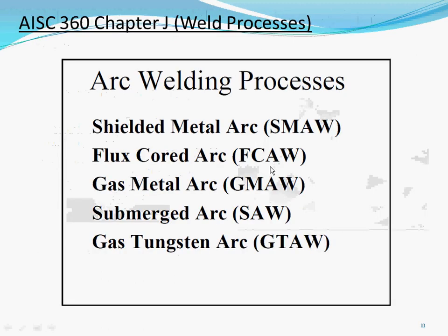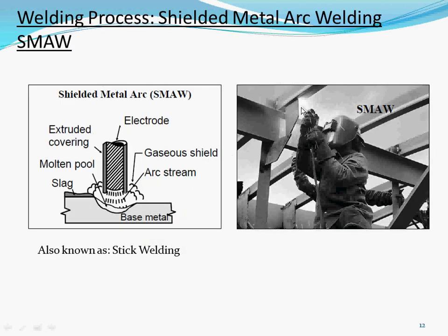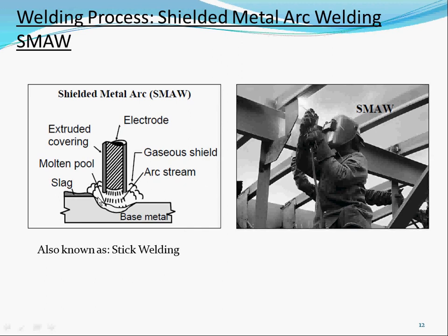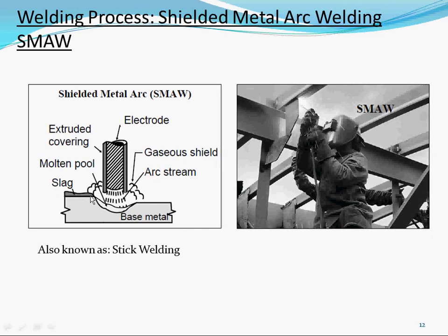I think this one is probably the one most people are familiar with. You actually have a stick. You stick it in, and then you could go and weld whatever you want. It's very portable, very easy to use. The equipment is cheap, and you probably see a lot of countries, when they start welding, they start doing this first. However, you do have what they call slag covering it, that you need to remove after each pass. So what that means is you don't want to get that in your pool.